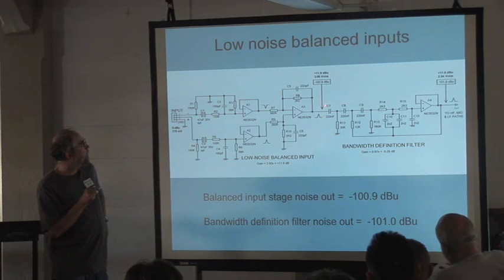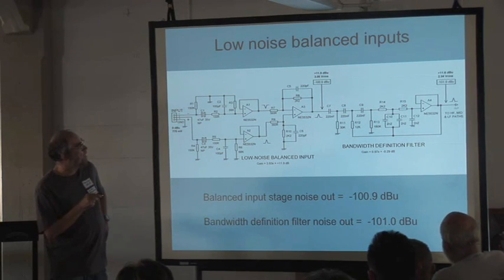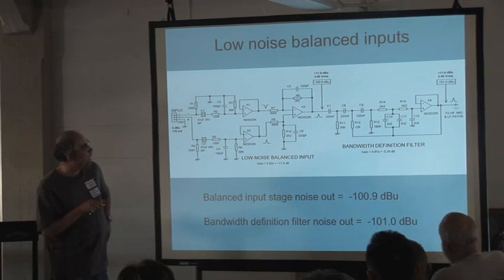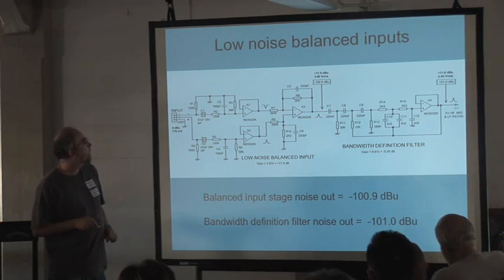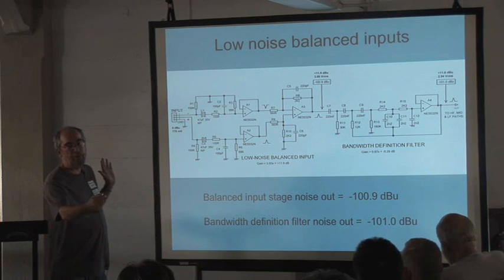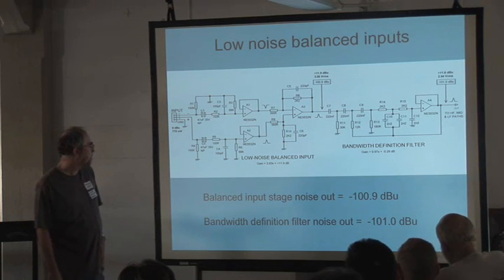You've got here a third-order subsonic filter, a third-order high pass, and you've got here a second-order low pass. And you can see they've been cunningly jammed together in the same stage. So you've only got one op-amp to create noise, and saves money, saves power, saves everything. And that will only work for something like this sort of filter where the cutoff frequencies are very far apart. This I think is 20 hertz, and this I think I set to 50 kilohertz, I'm not sure. But they do need to be octave upon octave apart, otherwise it'll mess up the response.